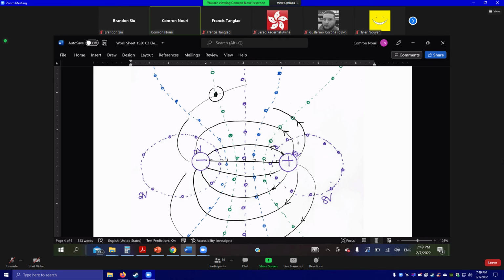Of course, it will be a curved line, but you can just measure from here to here. That's approximate anyway, so it's okay. For example, you may measure 5 centimeters, and 2 volts divided by 5 centimeters is 2/5, or 0.4 volt per centimeter, and then convert to meter, it becomes 40 volts per meter.